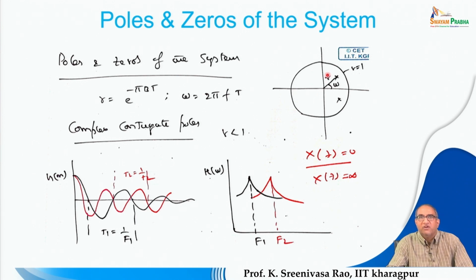So that way each pair of poles will provide you one frequency, that means one formant, and as I mentioned, the distance of this pole from the origin indicates what is the bandwidth offered by the particular pole, the root, right. Here, suppose the bandwidth is less, it indicates that the peak is sharper, that means the resonant frequency that is offered will be very sharp.